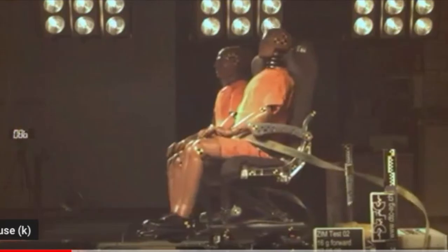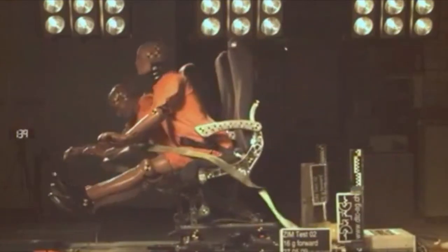If the passenger seat is a 9G seat, it really doesn't matter which component you modify on this seat, and there's really no limitation. You can use PMA parts. There's no issue at all. It is when the seat, for example, is a 16G seat. This is where you have to be careful. You cannot replace the bottom cushion of that 16G seat unless you perform the dynamic test.